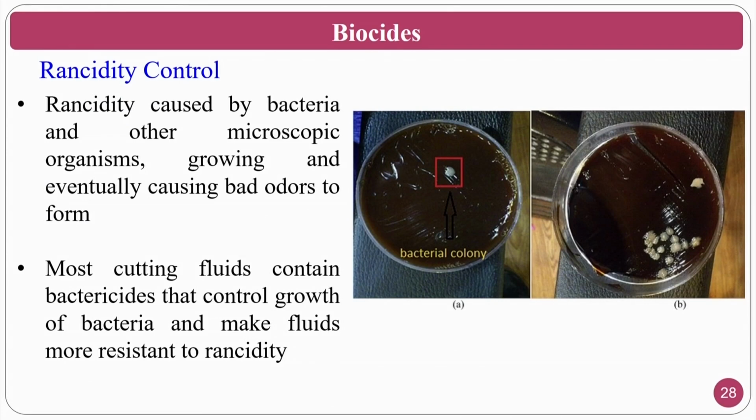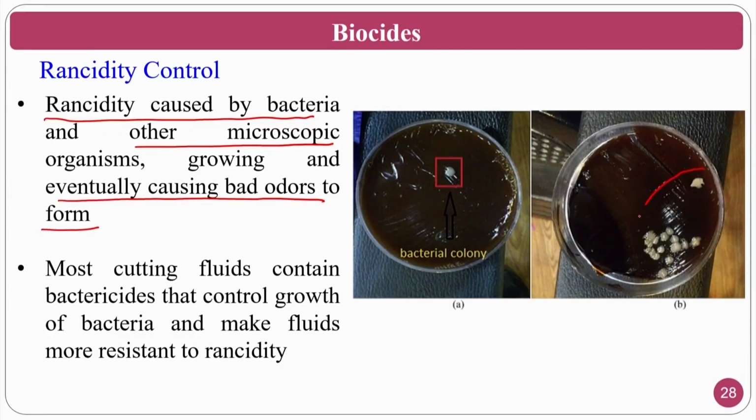Biocides are rancidity controllers. Rancidity is caused by bacteria and other microscopic organisms growing, eventually causing a bad odor from the foam. This is the grease. Normally cutting fluids and greases are common cooling as well as lubricating agents. Since we are talking about the grinding process, lubrication should be a primary concern, and for this, grease is one of the better lubricating media.